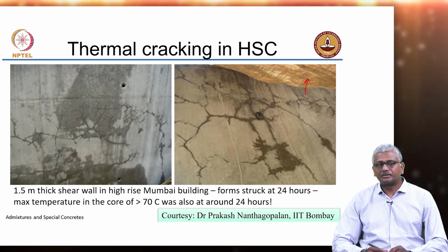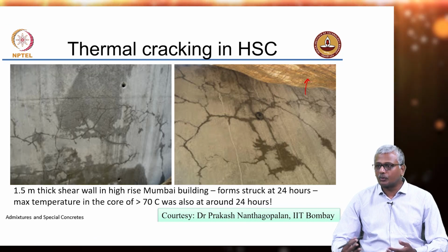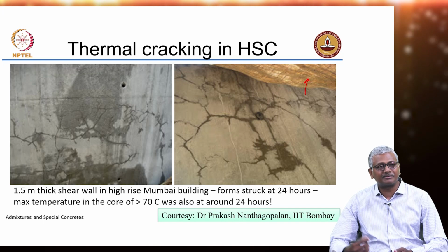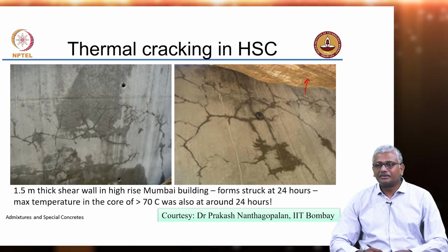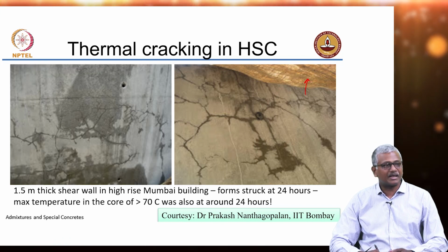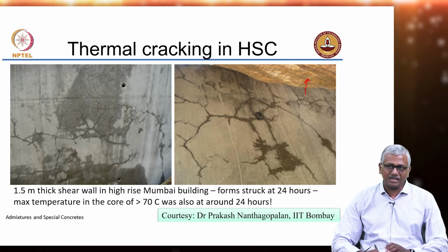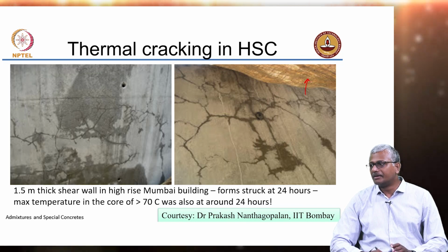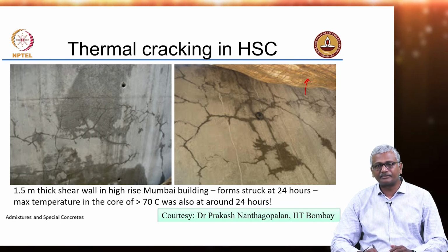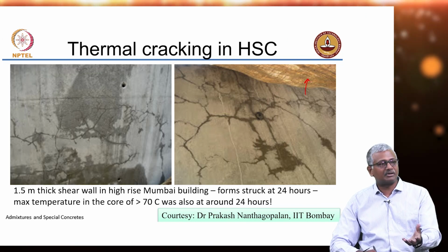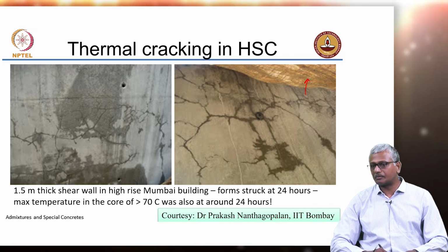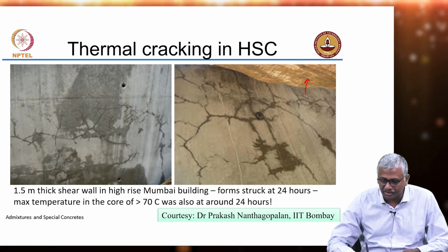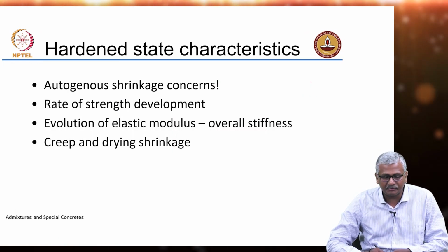Okay. This is very important for those of you who are going out into the field and going to be practicing concrete technology. Convincing your bosses to put up an ice plant in any situation is an absolutely important thing, because these days we are seeing massive concrete structures coming up. We need ice plants to give the ice flakes that can be put in the concrete for very efficient lowering of temperature. We will come to that again in the mass concrete chapter. So, those are some strategies by which you can do this.